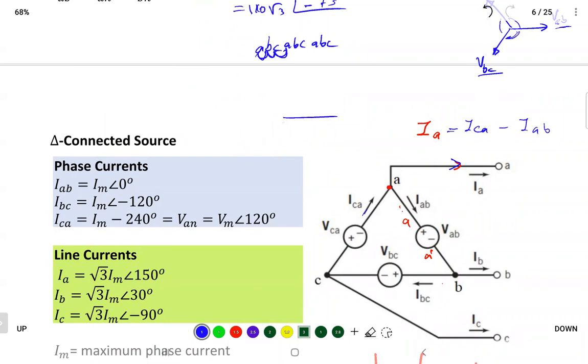You have the three phase here, A, B, C. And if you flip this one to the other side, we know that this is 120 degrees, so that will be 60 degrees. If you make the parallelogram and since they are equal, the resultant will divide it into two equal angles. That's 60, so that will be 30 and 30. That's how I got the 30 here. So the total will be 120 plus 30, which is 150.